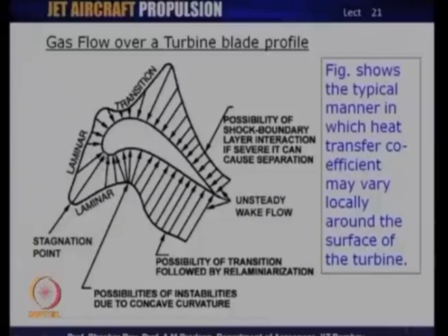So, the total temperature at this point is equal to the static temperature, and that is exactly what is felt at the stagnation point. So, this stagnation point is the hot spot of a typical gas turbine blade. Now, this hot spot is what everybody is most worried about, and we shall see very soon how this hot spot is expected to be cooled through impingement cooling from inside. So, this stagnation point is one of the problems of heat transfer cooling of typical gas turbine blades.